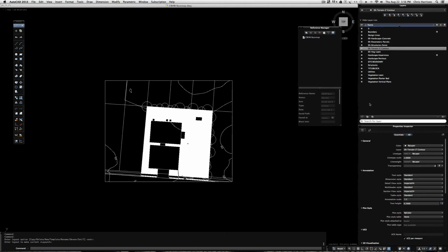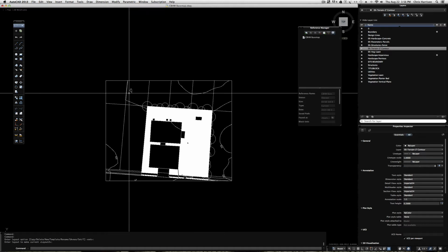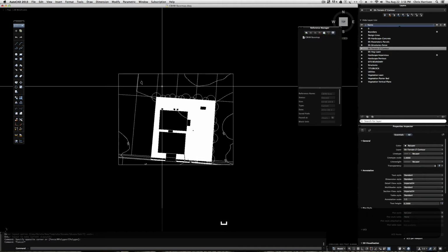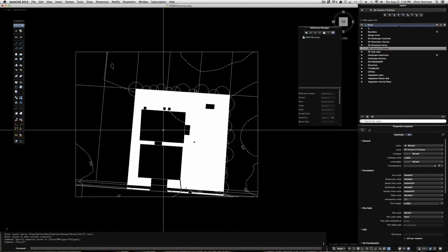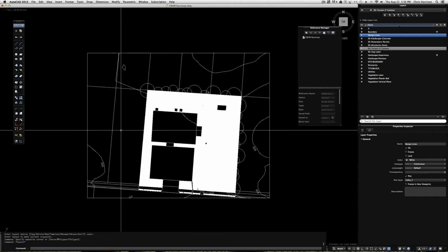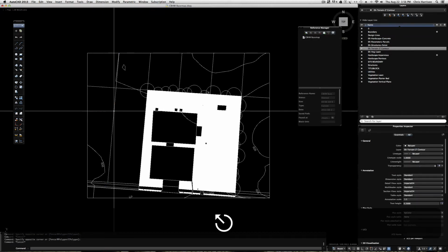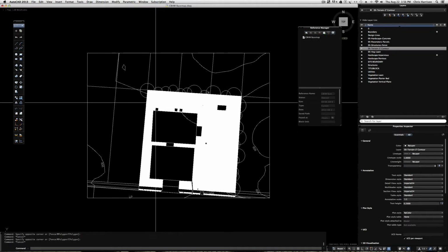So you'll notice that all these things are white, and one of the things that I want to first emphasize when we work in CAD with this is that we work with line weights. That means that each line will have a different thickness, which will help it read better, and that'll become more apparent when we print this thing out. And we have color. We have something called pen settings, which basically allocates a thickness of line, a width, to a color. So that being said, what I want to do is go through and change some of these lines to be different colors so they'll read better, and also change their line type, potentially their line scale, and their colors so that they'll print correctly, and again they'll read better.